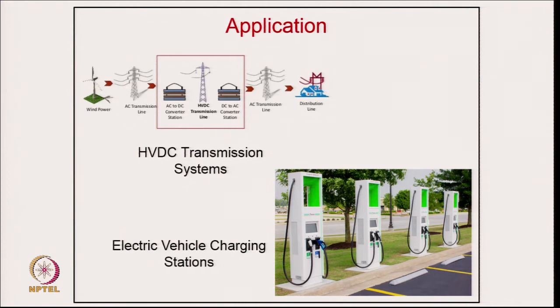Then coming to applications like HVDC systems. HVDC is quite an old application, since 1954. Earlier we were using thyristor converters, typically with passive filters, but nowadays we have started using voltage source converters, with the benefit that there is no need for reactive power from the AC side during contingencies or otherwise; virtually you are able to generate the reactive power by the voltage source converter.